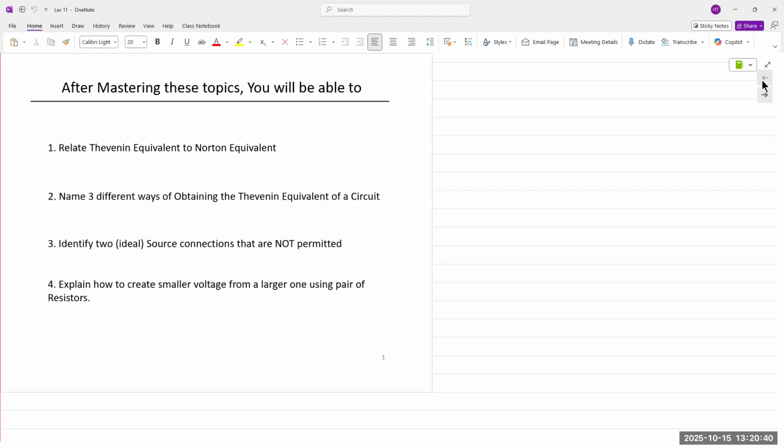Leon Charles Thevenin was a French telegraph engineer in the late 1800s, around 1880 to 1890. He postulated a theory that if you have a large linear circuit comprised of linear sources, linear elements and linear components, you could represent the entire circuit containing multiple sources and multiple resistors, and describe it with only one voltage source. Of course, that voltage source would have a resistor in series.